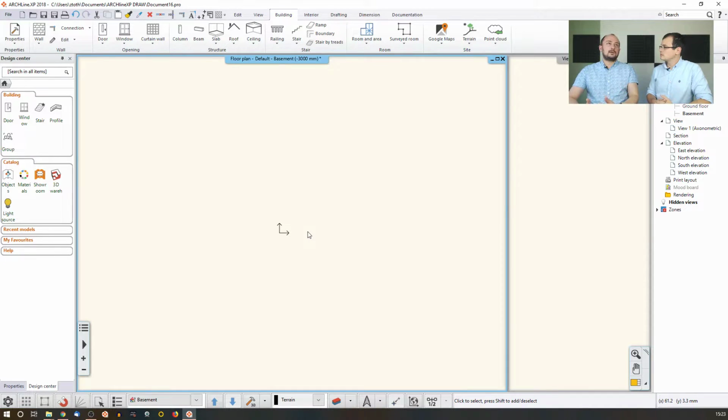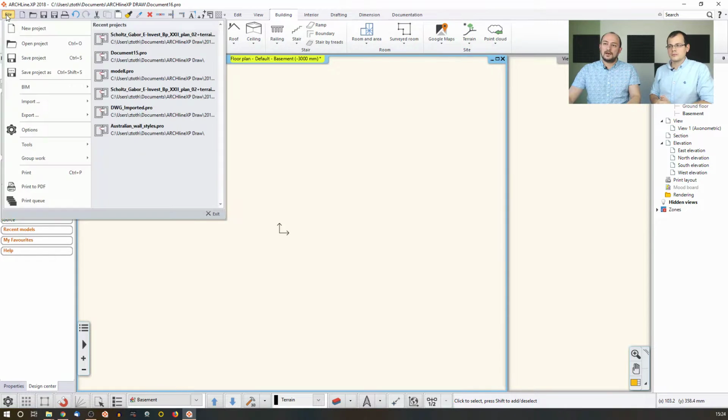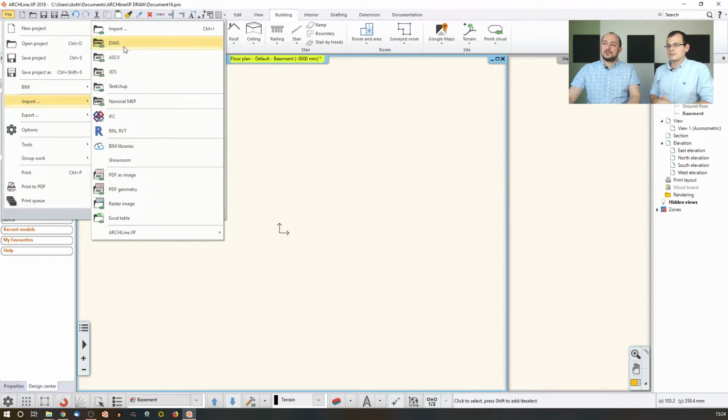And then when you have something as vector graphic content, like the DWG file, in that case I won't open it as a terrain because I know it's not a terrain. It's a drawing, which contains lines of the terrain as well. Even if I would do that, nothing would happen because there's no terrain information in that. So I just simply go there and File, Import DWG.